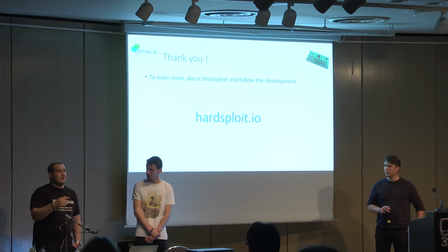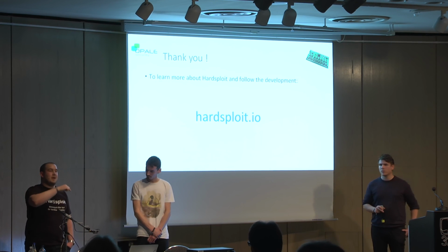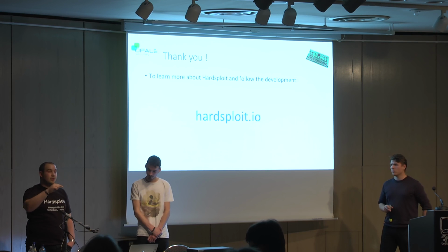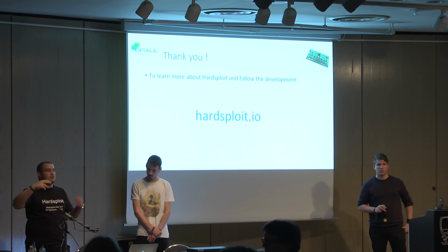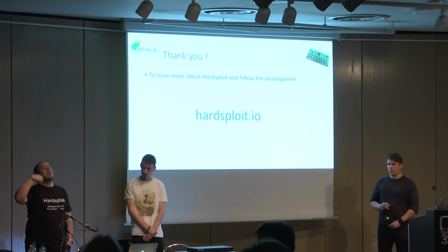So in fact, you have graphical interfaces, an API in Ruby, communication with the microcontroller, and the microcontroller communicates with a custom internal protocol with the FPGA. And inside the FPGA, yes, you have 2 modules. We have the Hardsploit core, to create the communication with the microcontroller, etc. And now we have a module.